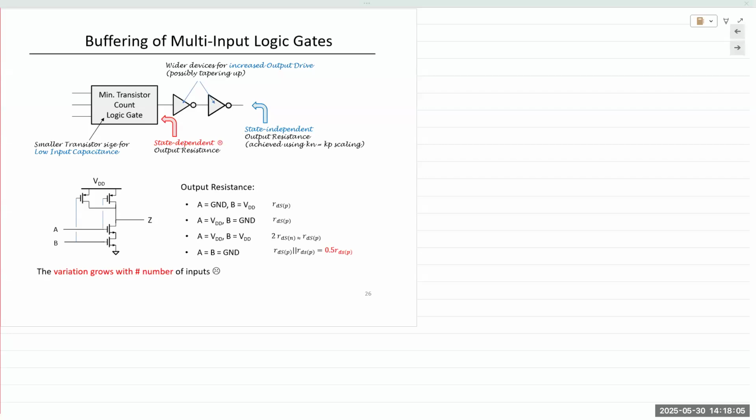So oftentimes it happens that the output of the first gate is not sufficient to drive the input of the second circuit that is connected to the output. And in those cases, we need to isolate the two circuits. One example that we saw in the lab was when some students were trying to drive an LED from a counter or comparator circuit, and the output of this logic gate or logic circuit may not be sufficient to provide the voltage or the current. If that's not sufficient, then the LED is not going to turn on, or if you're connected to a motor, the motor is not going to turn on, the solenoid is not going to turn on.